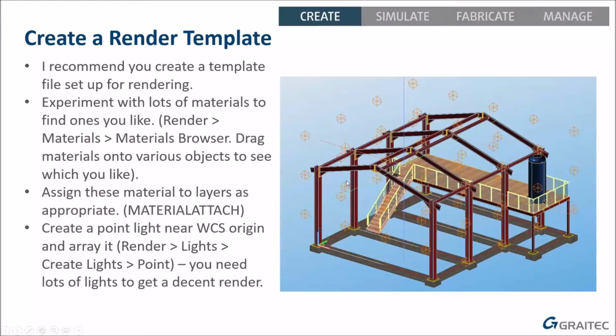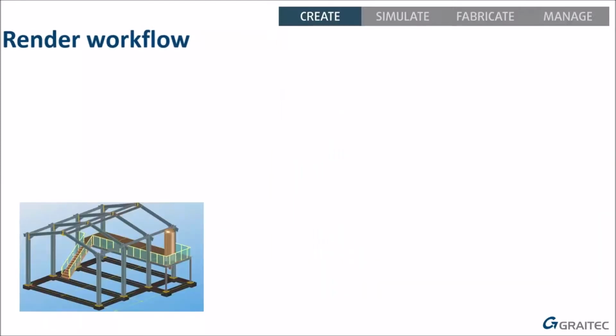No model in the file, just the light sources, and you've assigned the textures. You don't have any model in that file at this point. Save that as your template from the rendering template. That is your empty file ready to use for rendering in future. Then that's a one-off job. You create that template and you're going to use that template in all 3 workflows I'm talking about for the rest of this webinar. So spend half an hour, even, however long it takes, a couple of hours. It's worth spending time on that template because that will save you time later on.